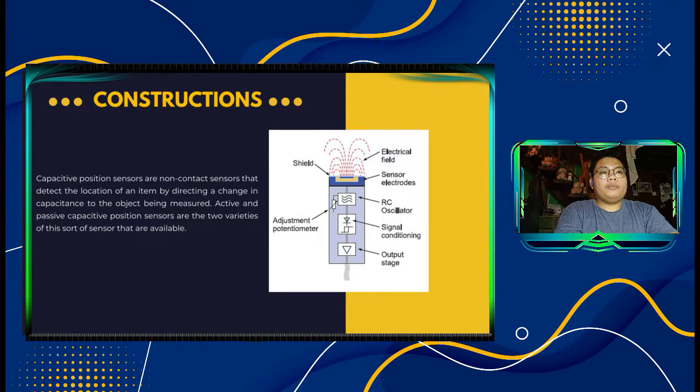Capacitive position sensor. This is a device that determines the displacement of two parallel plates. One is the sensor and the other is the object or material that the sensor measures. The measurement technique of capacitive sensing is non-contact. There are no witness markings, part distortions, or probe wear since the system does not make contact with the part. High volume measurements are feasible since there is no sensor cycling time. They are perfect for sorting applications with massive volumes of data as well as high bandwidth measurements.